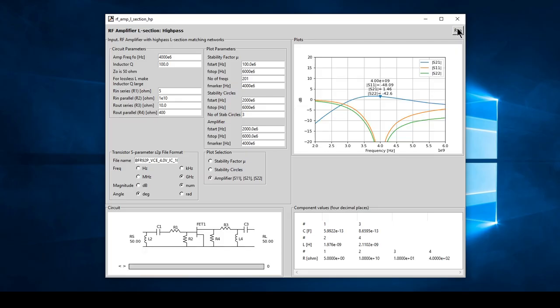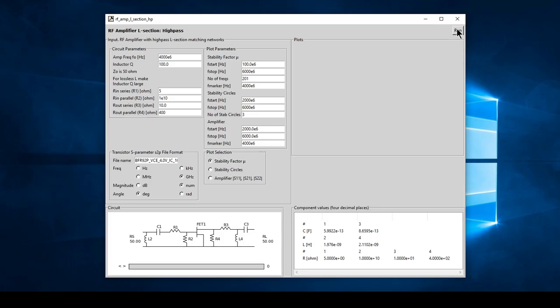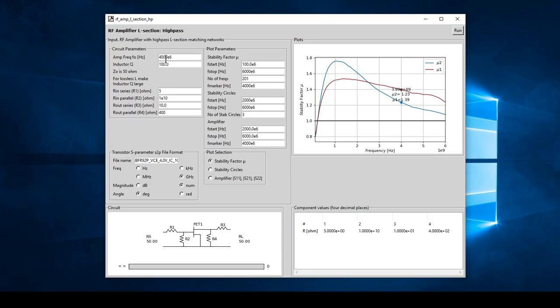Okay, it hasn't got much gain at that frequency, so there's not much use. So let's go down to a lower frequency, down to 1 gigahertz. Let's do the design at 1 gigahertz. And then the stability circles can start at 1 gigahertz. We're still within the stable region, so they're all going to be outside the Smith chart. And let's then have our marker also at 1 gigahertz. Over here we can also have a marker at 1 gigahertz, and we can run that.